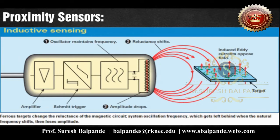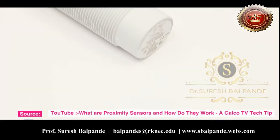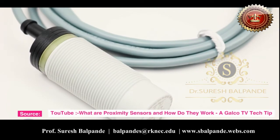The basic difference between inductive and capacitive is, in inductive, a magnetic field is produced because there is a coil and we pass current through that coil, whereas in capacitive, an electric field is produced because it is based on a capacitor. So there are plates. The inductive proximity sensor requires a metal target, whereas a capacitive sensor may be suitable for a plastic target.